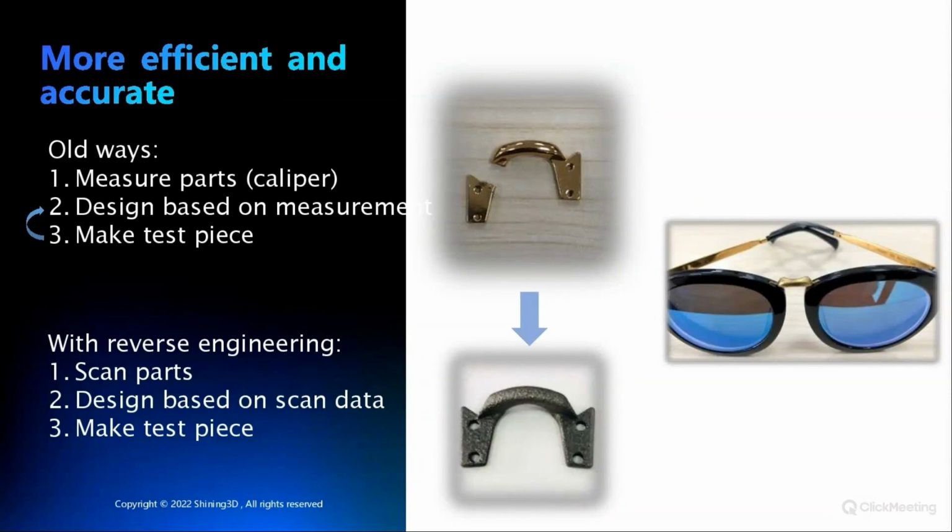Here you see that we just scanned this middle part of the glasses and we reverse engineered it in Solid Edge. Then we reprinted it with a metal printer. Then we just did some surface finishing. And finally, we repaired this pair of glasses. And this is actually how reverse engineering can help us. This is one of the applications: to repair something when there are no spare parts on the shelf. So you can use reverse engineering to model the broken part and repair the thing.